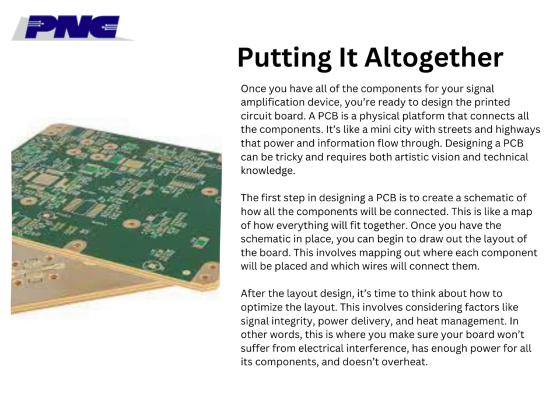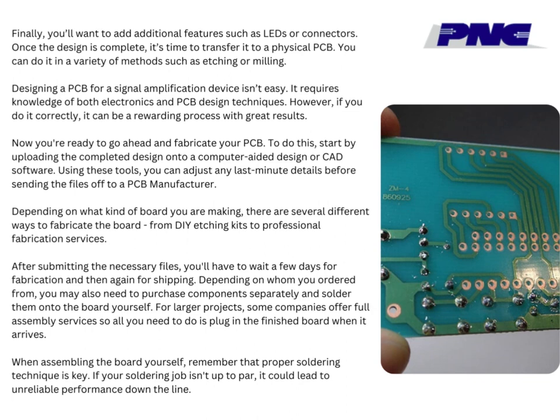After the layout design, it's time to think about how to optimize the layout. This involves considering factors like signal integrity, power delivery, and heat management. In other words, this is where you make sure your board won't suffer from electrical interference, has enough power for all its components, and doesn't overheat. Finally, you'll want to add additional features such as LEDs or connectors.